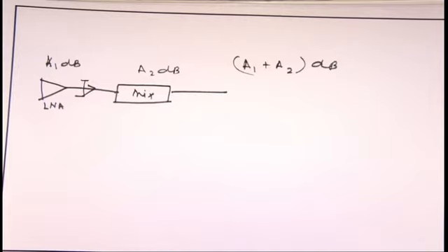You will never get 18 dB, you will get 10 dB or even 9 dB, something like that. Then you remove these 50 ohm terminations, and you club the LNA output with the mixer, and then have an impedance or transformation block which will actually match both the LNA and the mixing block. So, that is the trick I am giving.